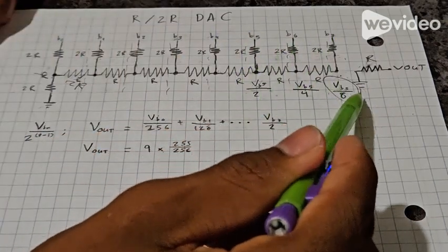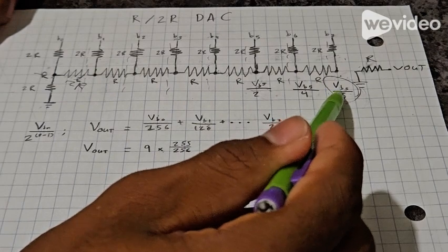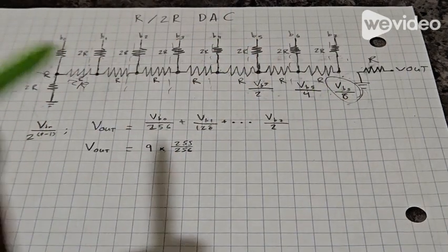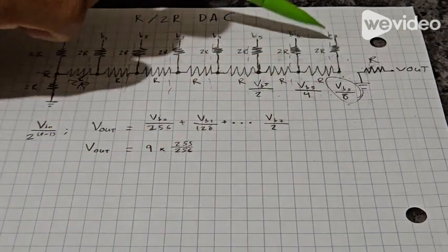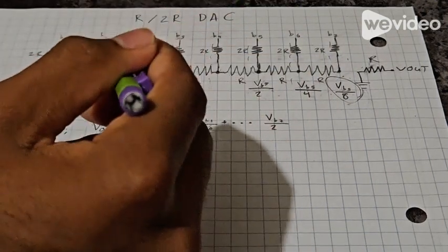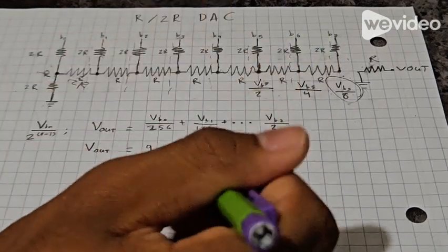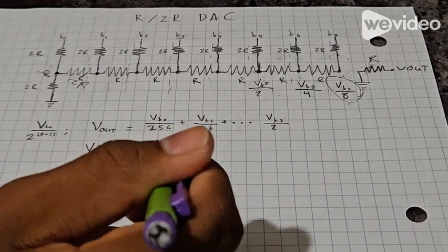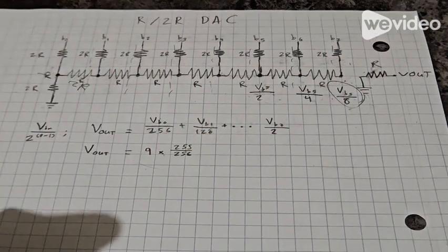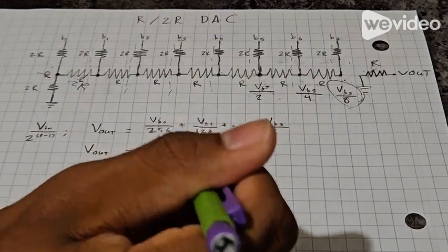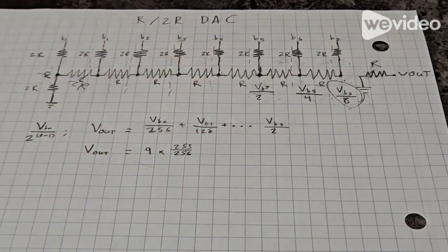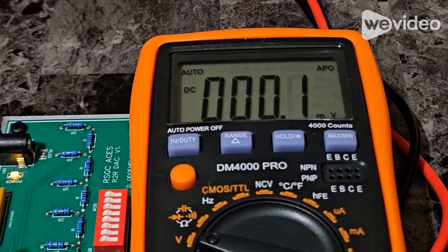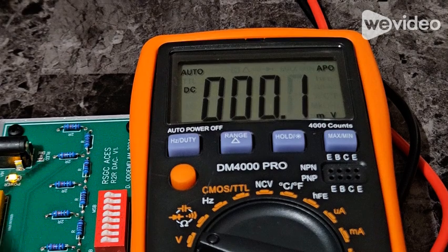And we repeat this process 2 more times to get the voltage contribution of bit 5 is the total input over 8. By repeating this process for every other bit from bit 0 through bit 7, when assuming a 9-volt power source, the maximum voltage output we can get when turning on every bit would be 9 times 255 over 256. Meaning we get 9 times 255 over 256 volts as our total voltage output. The last thing that the superposition principle states is that if you want to find the voltage contribution across multiple bits, the bits can be summed.